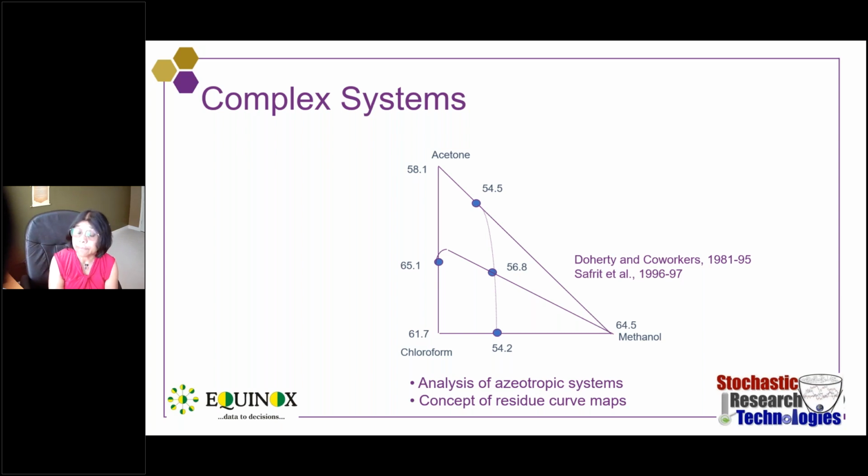can actually predict what can happen, or how many continuous columns are required, how many fractions, how the cuts in batch distillation are required, whether you want to add an extractive agent, how you add an extractive agent, how you add a solvent, as a function of the residue curve map. And that was very, very useful and essentially covered the area of both continuous and batch distillation. A lot of people have worked in this area, and essentially this is useful, as I said, to decide even what solvents can be used.